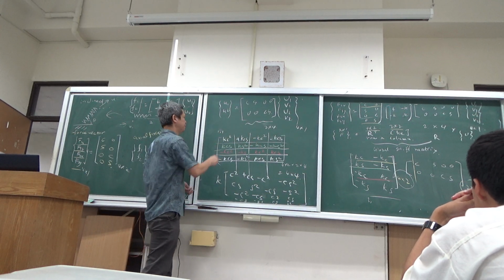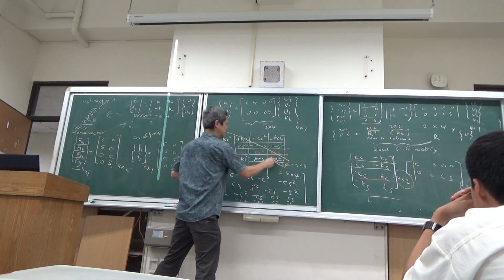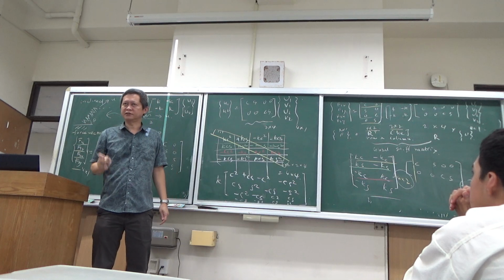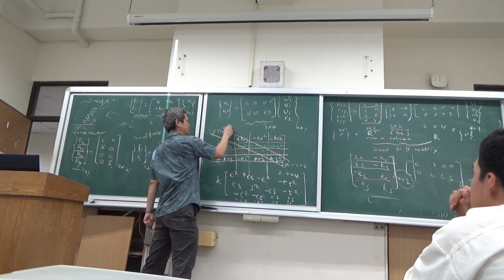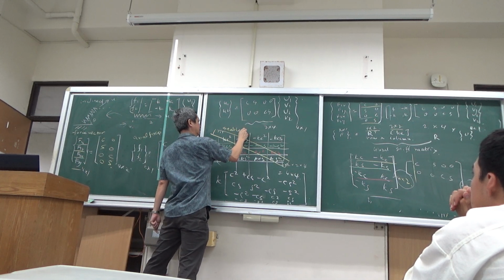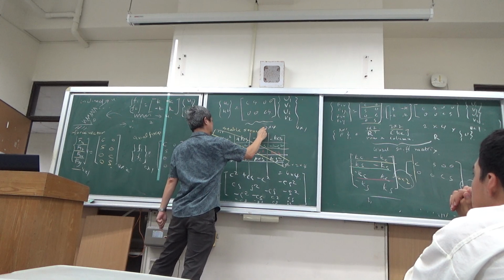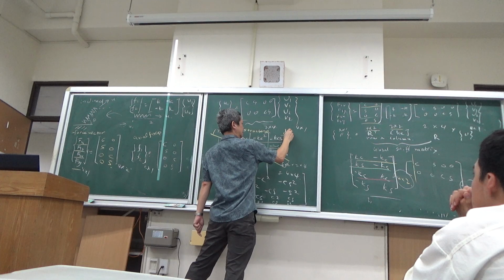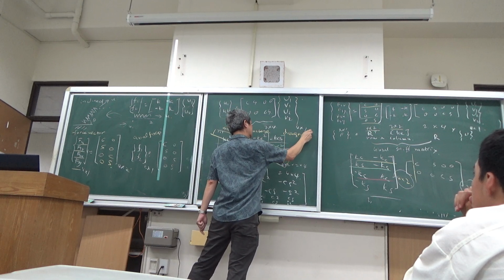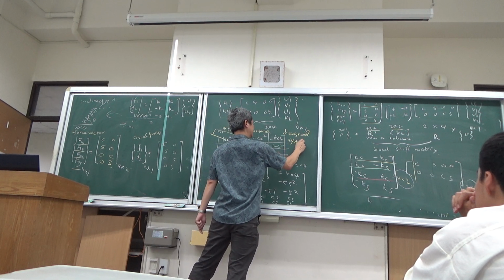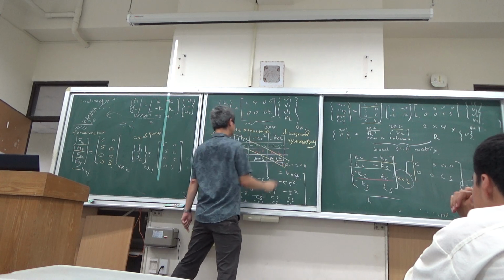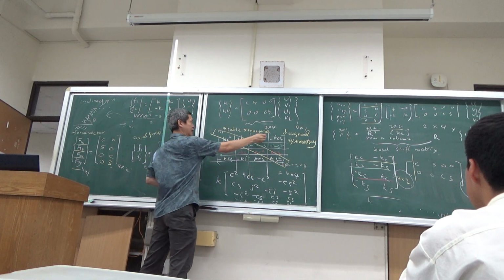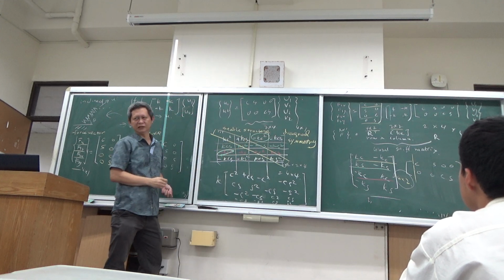A quick way of checking if you are writing the right thing: there is one feature that we can always make use of. For any stable structure, their stiffness matrix must be diagonal symmetry. Meaning anything on the opposite side, you must find the identical.